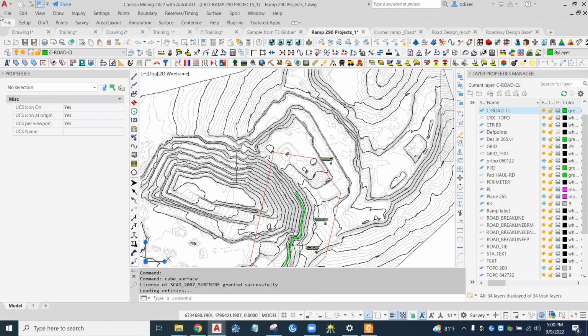Instead of that 45% grade or whatever it is, they want to find, say, a 5% grade and start at the top, and it'll just walk down that slope. When those slopes are nice and even without all of those in and out little juts, it just finds and draws this nice little corkscrew line that wraps itself around the outside edges of those fill banks.